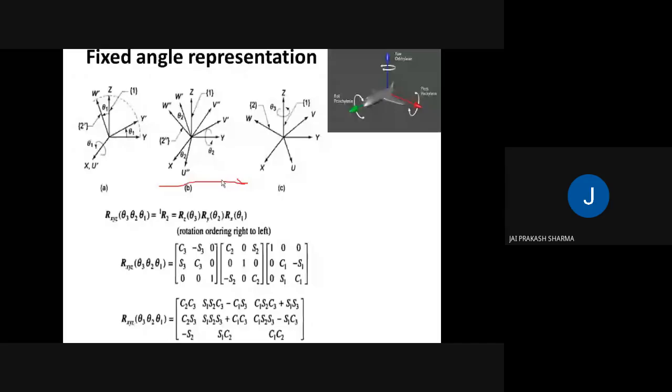For getting the final transformation matrix, you have to perform a rotation. So if you need to calculate the final position, following a sequence in such a manner, that is xyz a b c, the final robot rotation we calculate. Okay. This is the final transformation matrix which is 3 by 3. So in such a manner you can find the final rotation values of your robotic arm. Okay.